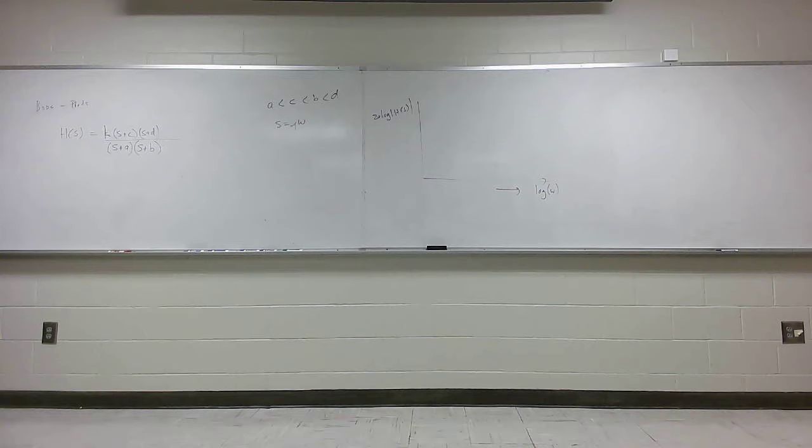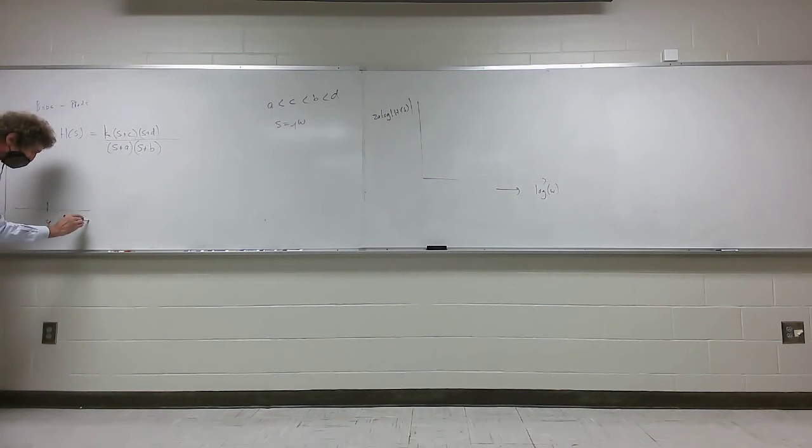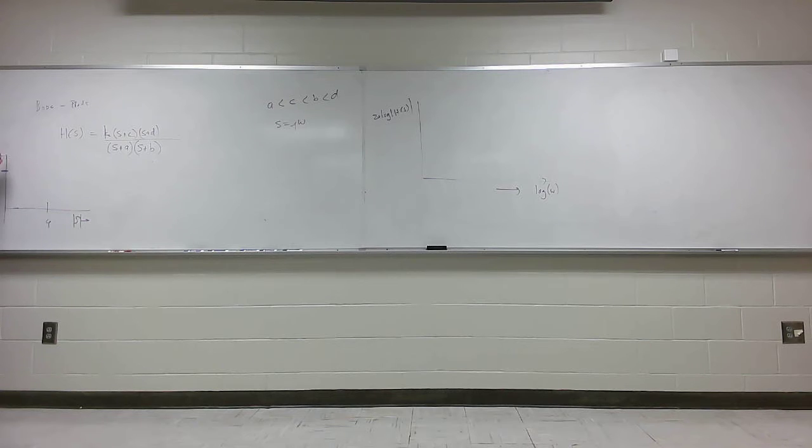But if you were to plot just that versus A, for values of S or of omega, j omega. I'm going to use S here, the magnitude of S. For values less than A, this plot here would just be 20 times the log of K, isn't it? It would stay there until I hit A. Do y'all remember doing this class?